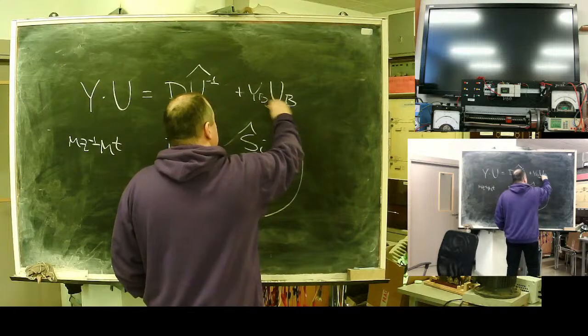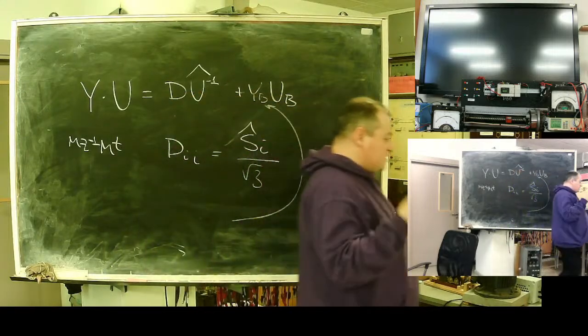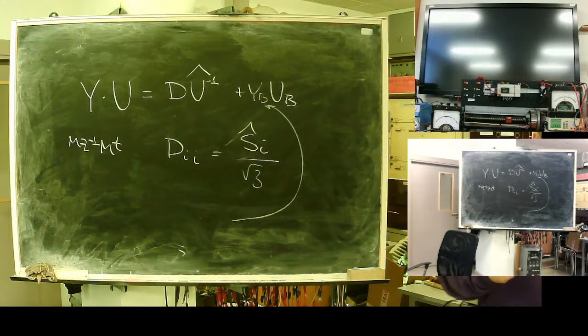This one is needed because in such calculus, the base node is not ground. Base node, or slack bus, is a larger power plant. Actually, it's usually a large power plant, but a power plant with active voltage control system, keeping high voltage network voltage.